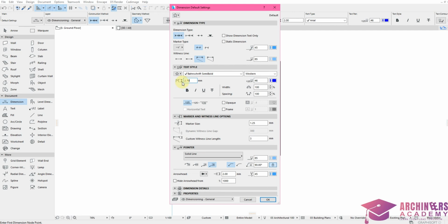So you will not design something without a visible dimension. The dimensioning, the numbers must be visible. Very important. And make your marker size 3 or whatever, because you're customizing it, whatever makes this thing visible. Your arrowhead is okay, so let's click OK and we'll start dimensioning.